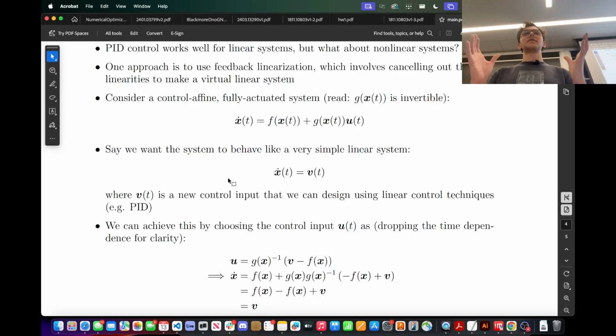I have 4 control inputs, which you can think of as the propeller forces, or alternatively and completely equivalently, as the 3D torque that I exert on the vehicle, and then the force that I apply, which is aligned with the propeller. If my drone looks like this, I can apply a force like this, and I can also apply a full 3D torque.